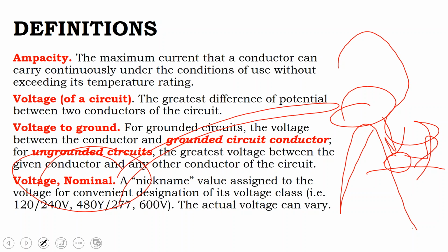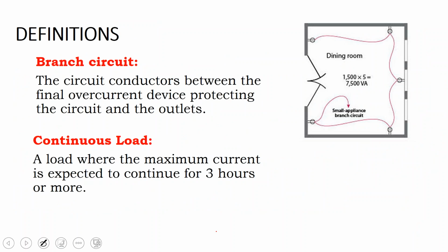And we also have to be more careful when we're combining just dumb solar inverters that are not intended to be energy management devices, but are just designed to dump all of their power onto the grid, or all of their power into a battery bank, that the system is well sized so that we're not exploding our batteries or backfeeding the grid when we're not supposed to, or backfeeding a generator. And there's a number of ways we can do that. And often these ways have to do with mechanical switching so that there's a hard disconnect. Talk about that a little later.